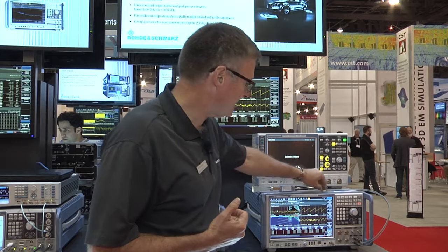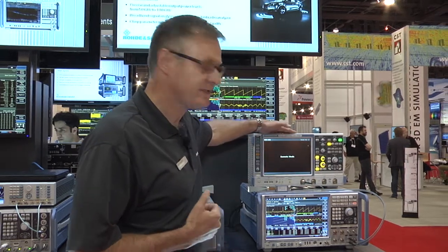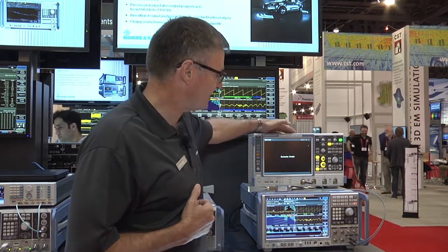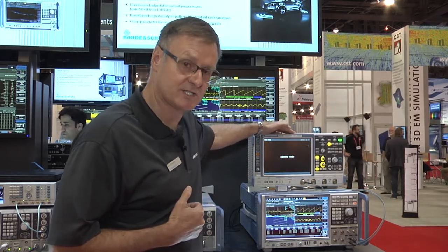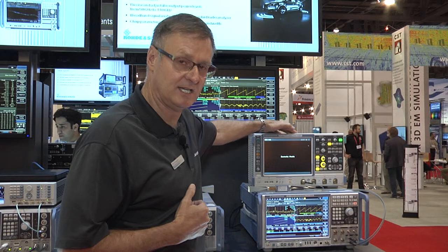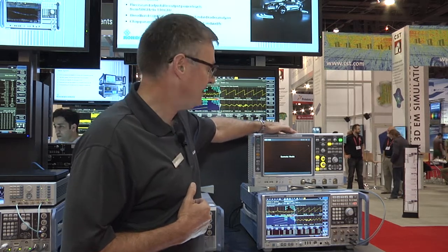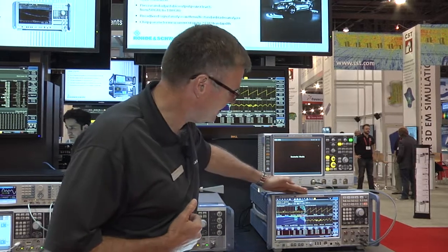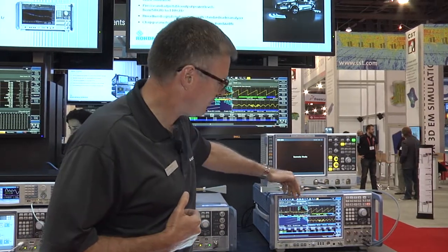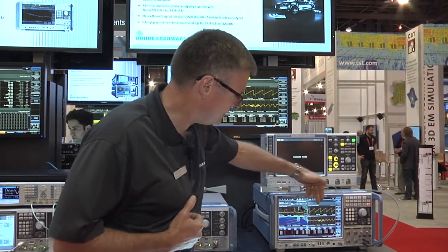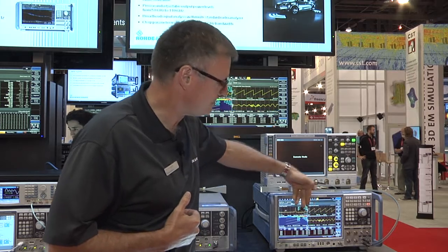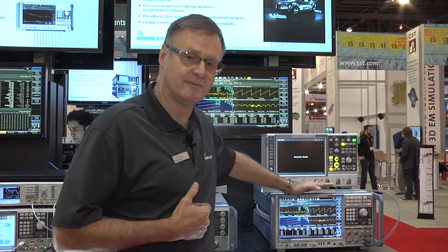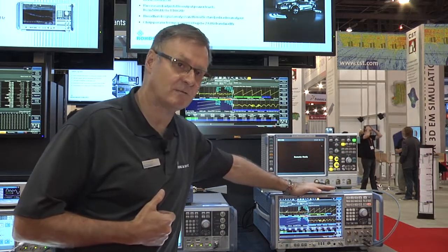That signal's coming around into the front of this RTO oscilloscope. So the analog signal coming into the oscilloscope is being digitized by our high-speed A to D in the oscilloscope. And then we have digitized IQ samples being routed back into the analyzer for the pulse demodulation and display down here. So that's one side of the high-frequency millimeter wave offerings.